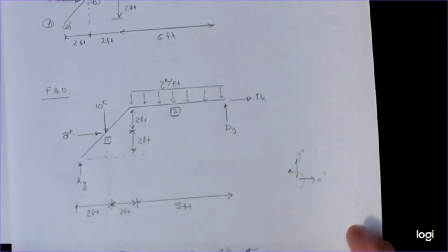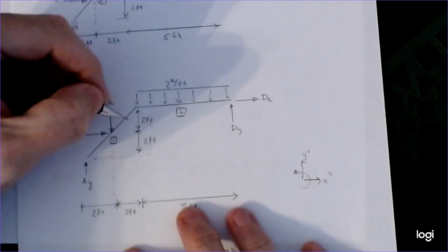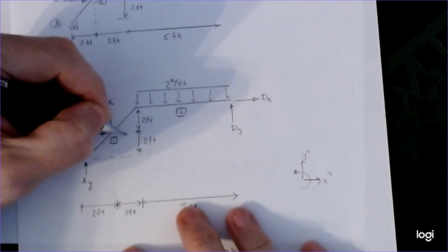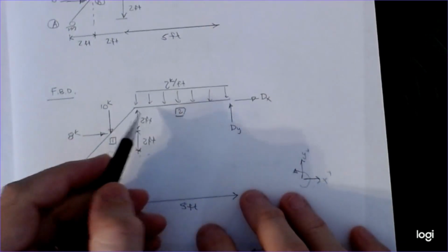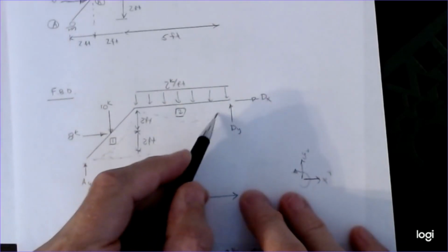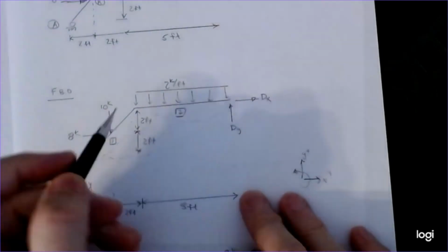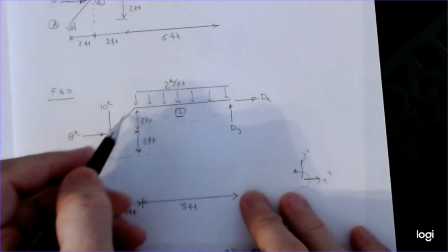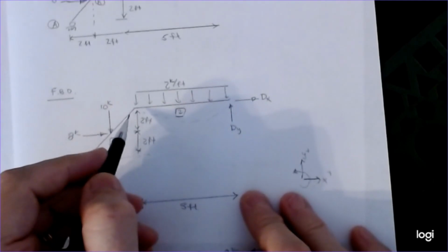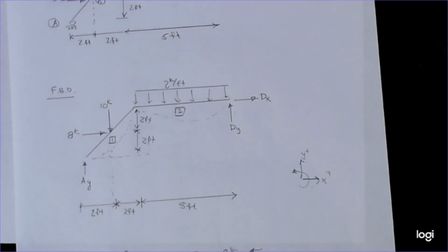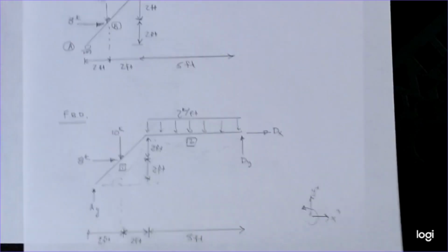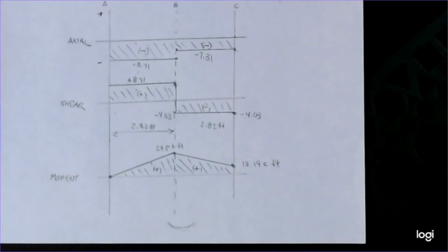If I put this member back up here, this is bending down something like that. Then this joint will maintain integrity, and clearly this other member will do something very similar. That joint maintains the angle that it had before and after, and that becomes an important idea when we get into some of the more advanced analysis methods: the joint continuity that exists between one member and another. That's another difference on the frames that we'll talk about a little later as we move forward in the process. So anyway, hope that wasn't too confusing. We'll stop there.